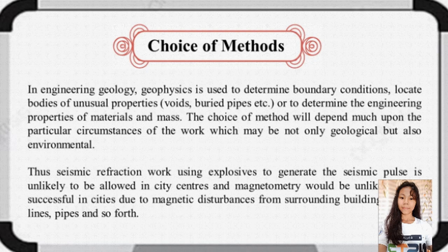Thus, while seismic refraction methods are relatively useless as a means of finding underground cavities on a site of which nothing is known, they might be able to detect zones of disturbance caused by the presence of cavities in a coal seam whose location is known.